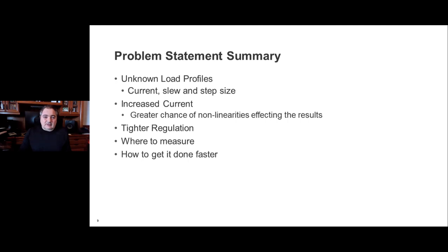As we go down in geometry, as the functionality of these devices increases and the gate voltage goes down and the vSynth or the vCore voltage goes down, then the regulation is tighter, right? If the voltage goes too high, you can damage the device. If the voltage goes too low, then you have a signal integrity issue. You could lose the data. You could have a data integrity issue, more importantly. And that obviously is what we're here for. That's why we've all got jobs in power management